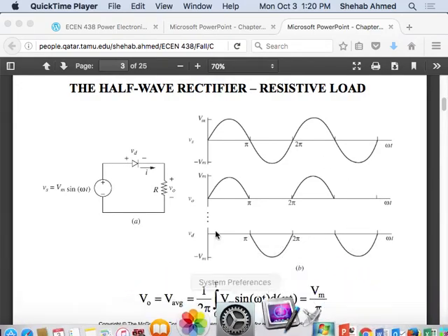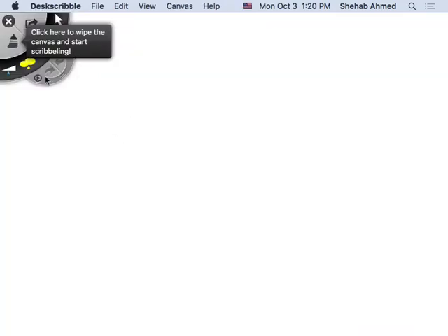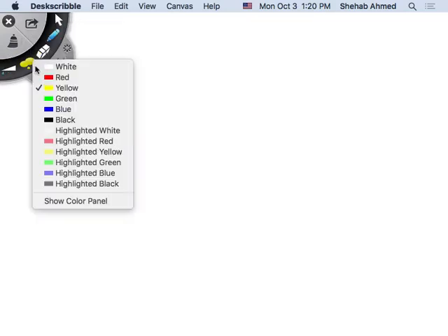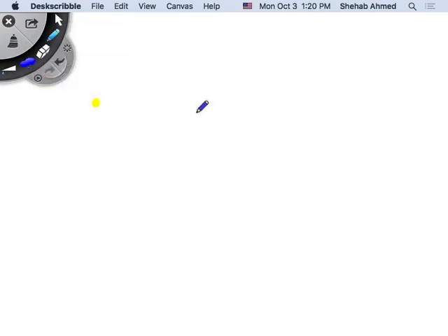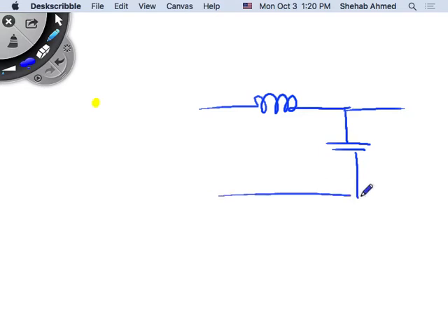No. For power applications, you don't want to use op amps. Otherwise, this op amp will have to process the full power, right? For power applications, you have to use an LC filter typically. That's what you would use to connect to the grid for a single phase converter.